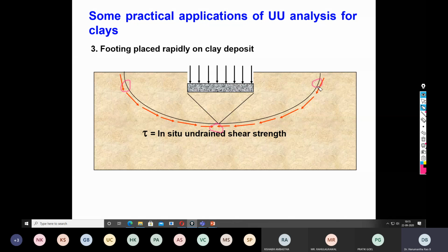If you look at the development of the failure plane, we always say it initiates at one point. We do not know where that point is. The entire failure plane will not develop instantaneously. It is progressive. It initially starts wherever there is maximum stress and least resistance.